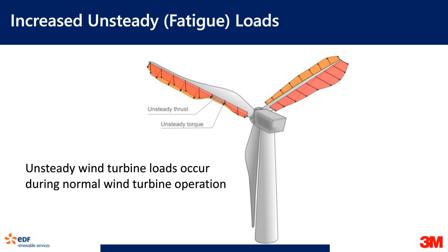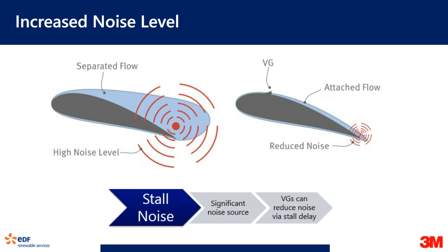So another factor because of the aerodynamic deficiency is that when you have the boundary layer flow separated, it can lead to noise due to stall. Many times this is a big problem in the industry, especially if you have turbines very close to a residential area. And many times we see this in Europe, where a big challenge is noise. Many times we focus on adding attachments to just address the noise, but sometimes correcting the aerodynamic flow alone can even increase the noise.